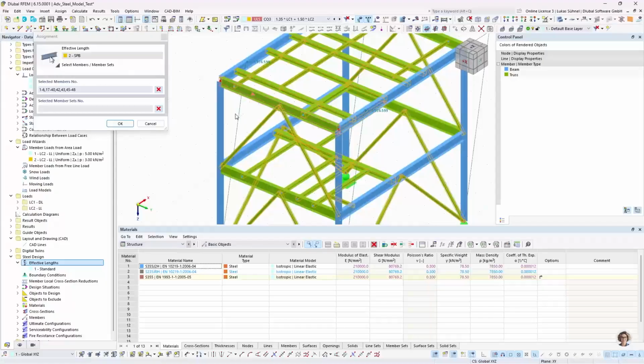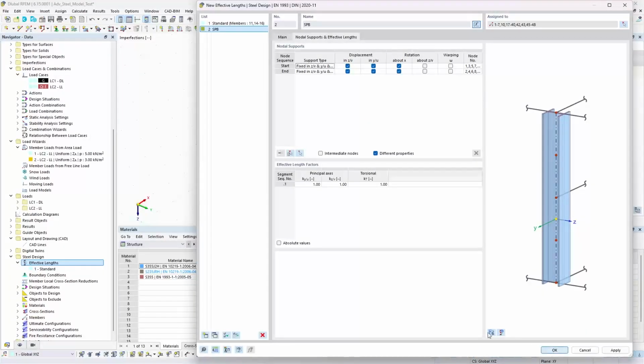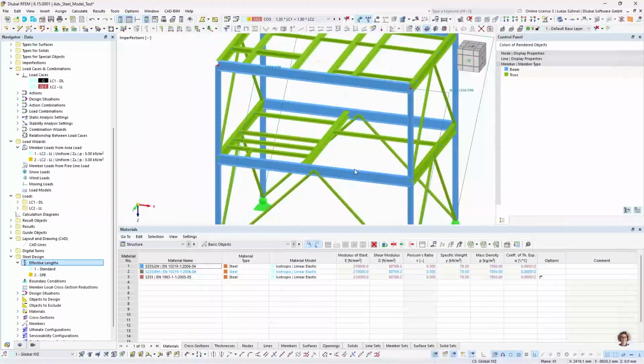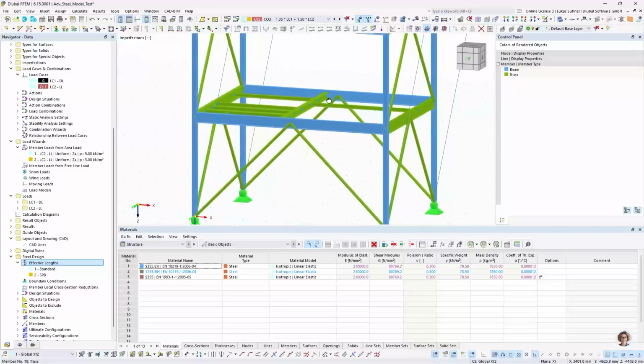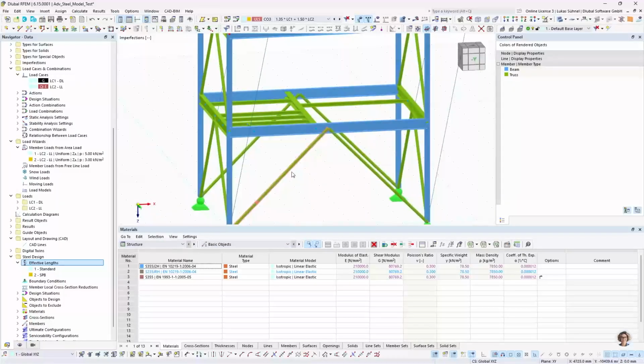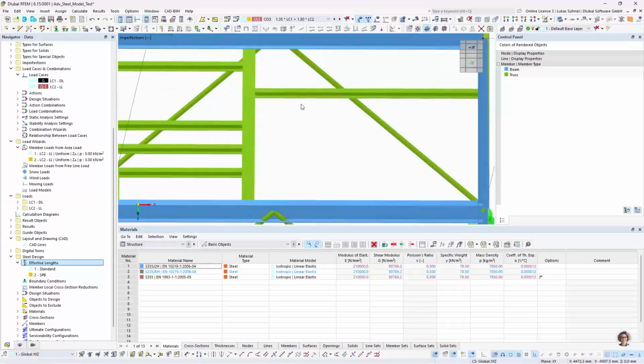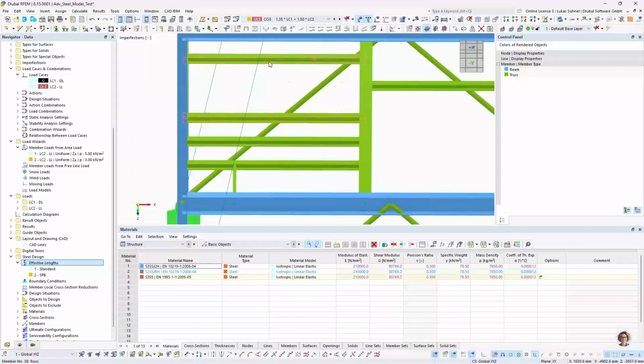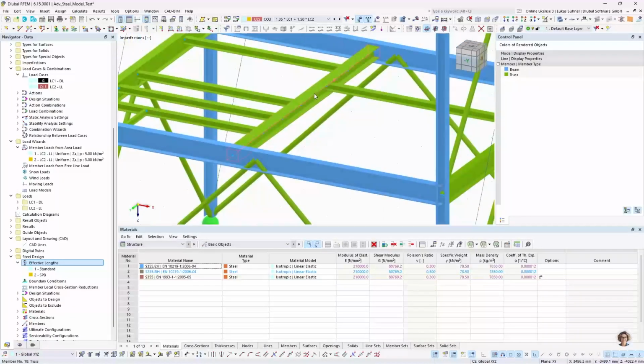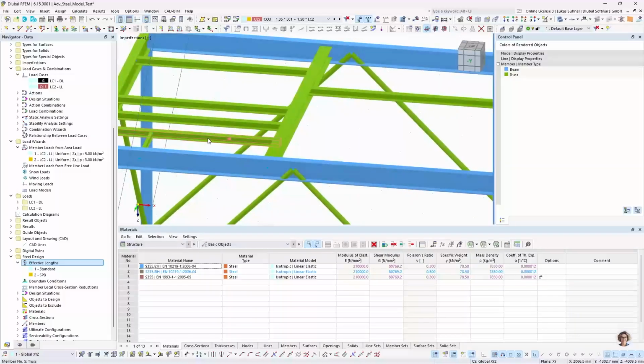And also these two main beams here. Okay. So what is my idea behind that? Well, I think it's easy to understand for these diagonal beams, and maybe also for this one here and this one and so on. But now we could argue about this beam here, this crossing beam. It is, of course, supported on both ends, but maybe there's an additional horizontal support by these crossing beams, in these inner smaller crossing beams.